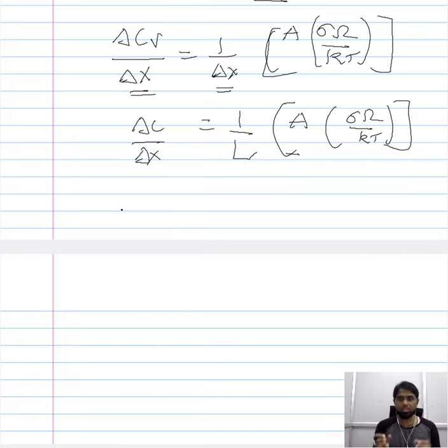Only because we are holding the material at high temperature do all these factors become relevant. That is, the role of stress in the concentration of vacancies is relevant only when you are talking about high temperature. When there is a role of stress on the number of vacancies, then the nature of stress also influences the vacancies. Because of this, we have a difference in the concentration of vacancies, and that difference we have now translated to the gradient.